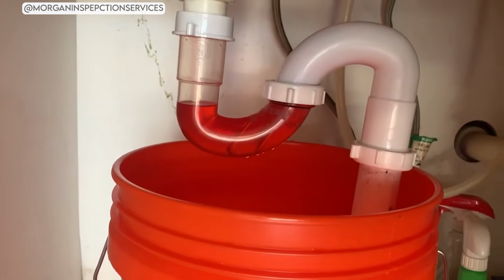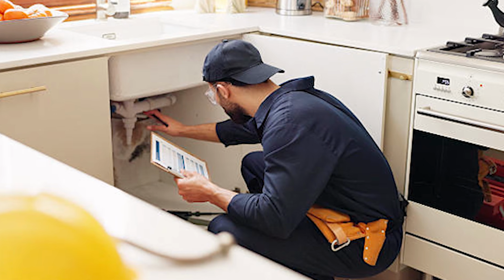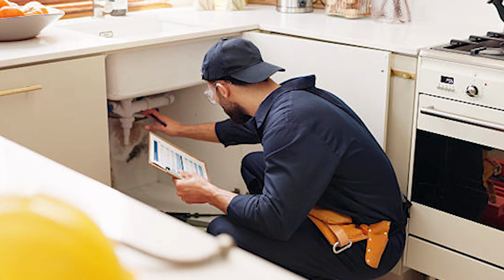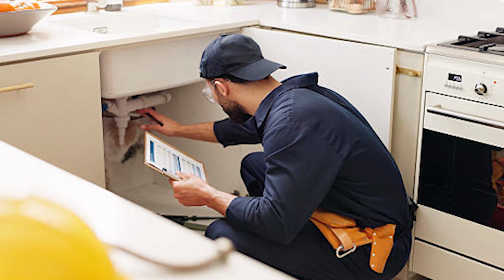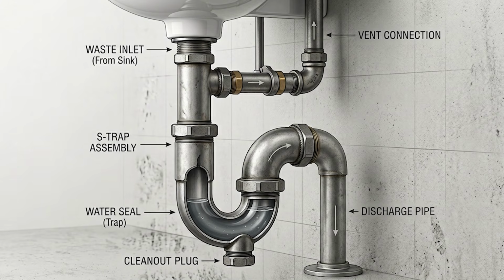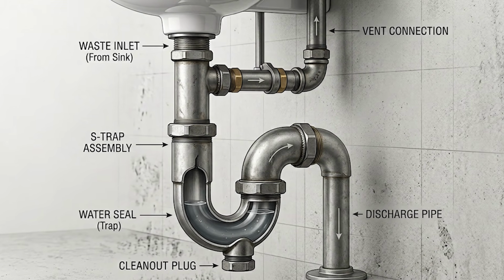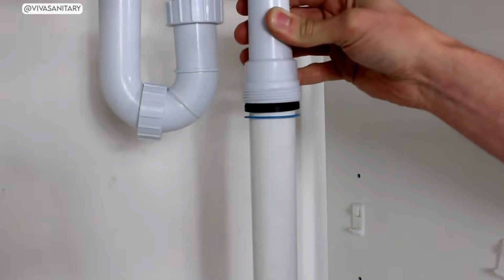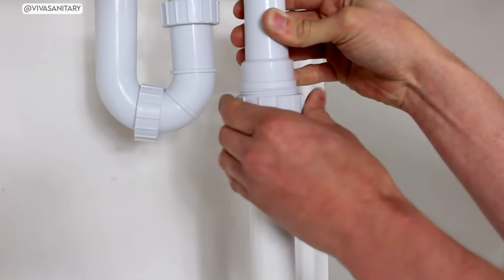It was not until plumbing science caught up and code organizations studied the siphoning effect in detail that S-traps were formally prohibited. So if your home was built before roughly 1980 and the plumbing under your sinks has not been updated, there is a very real chance you are living with S-traps right now.